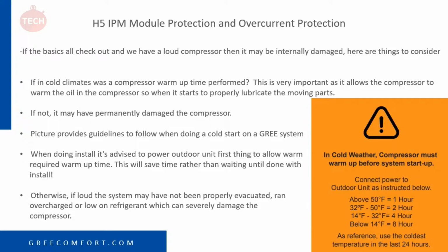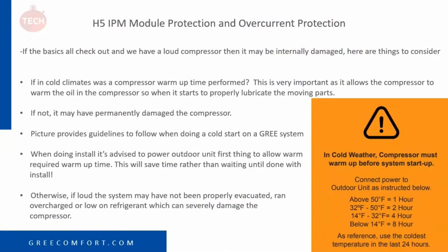What I always tell contractors to do is, when you get there to do the install, the first thing you want to do is just hook up main power to the unit. That way we start warming that compressor. And then just do the rest of your install, like piping, wiring, brazing, and vacuum. That way, by the time you're done with the install, it's just about ready to go.